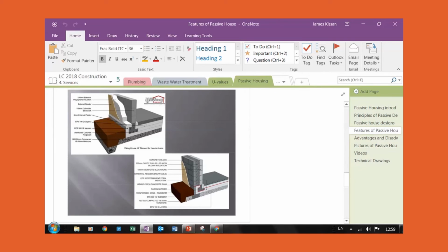And then if we look at this diagram, you'll notice that this diagram has one wall a lot larger. It's a 150mm wall, and then outside it we place our insulation, and then outside that we have external render. We've no cavity. We don't need a cavity.